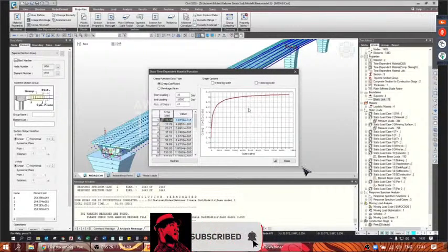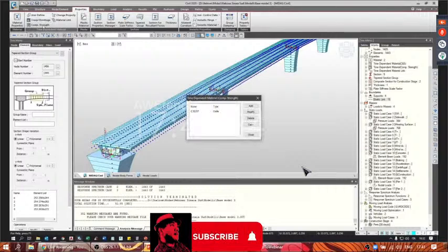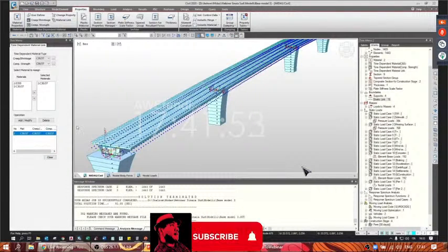We have defined also the increasing of compression strength here, choosing always Eurocode as European code and entering, in this case, the FCM value. Here is the graph already drawn. And we see that we reach the full resistance practically in 30 days. Finally, we assign the time-dependent functions to our material, which is already defined. Then we check the properties of the composite section during construction stages.